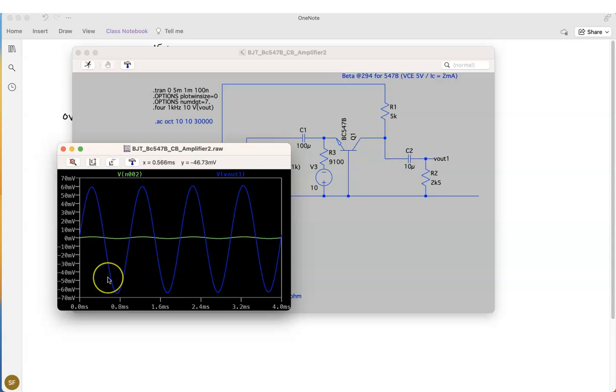So that's fantastic. Now it's never going to be exact. There's a bit of asymmetry. See, as the AC signal oscillates, this causes slight variation in the VBE because there's an exponential relationship between IC and VBE. Therefore, this is the reason why we get some asymmetrical distortion.